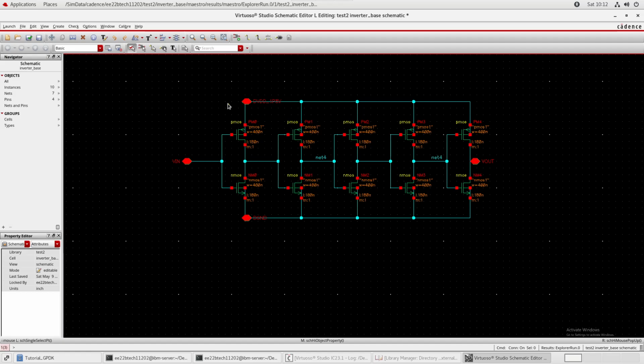I would recommend, especially for blocks in any hierarchy, never to leave the instance names as just I1, I2. That will create issues for you later and cause headache.